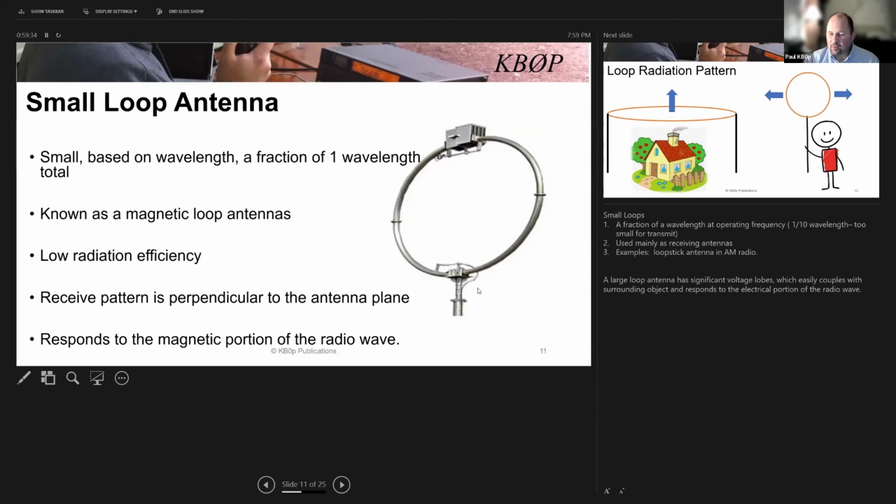And then if you have a high Q signal or high Q filter or high Q antenna, that antenna is going to be very sharply tuned to one specific frequency, but it's going to be very efficient at the frequency it is tuned for. But then if you vary off of it very far, it goes out of tune very quickly. So if you use a high Q antenna for receiving, it'll receive great at 14.100. And then you start going down to 14.050 or up to 14.150, you'll notice your receive sensitivity drops off almost right away. That's a good indication that it's a high Q circuit.